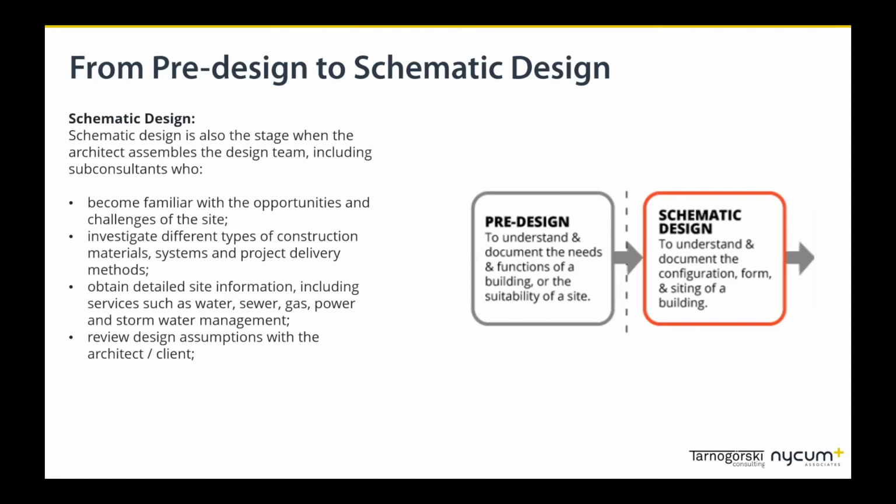Maybe this type of project, you're going to need a structural engineer. But depending on your water lines, your gas lines, your power lines, maybe there are implications for the architectural design, and you can't necessarily do what you were thinking in the pre-design, because maybe there's a big gas line that runs underneath it. Maybe there's only so much connection from the site to the street and that sanitary line or the water main.